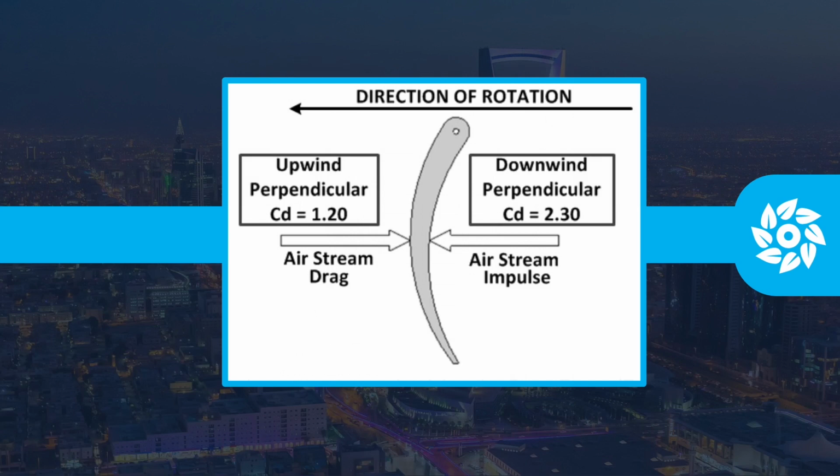The curvature of the flutter vane blades in the 3-blade configuration sheds a portion of the airflow striking the convex curvature into the concave section, increasing the impulse. The airflow striking the convex curvature creates lift in the direction of its rotation during a portion of the rotation to augment the impulse. The coefficient of drag 1.28 of the concave shape versus the coefficient of drag 0.295 of the convex shape lends itself to a differential of force impact to cause the imbalance, creating the rotation.